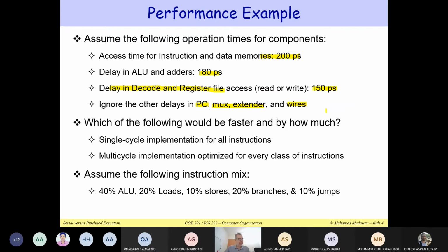And even in the case of a multiplexer, we have to look at the delay inside the multiplexer. Even the wires, people take the wires because they are dealing here with very fast clocks, and therefore the wire delay becomes important. As the wires become smaller and thinner, they will have higher resistance and capacitance. And therefore, it will take longer for a signal to propagate through these wires, and the wire delay becomes important. And even the wire itself, there is a delay in the wire.